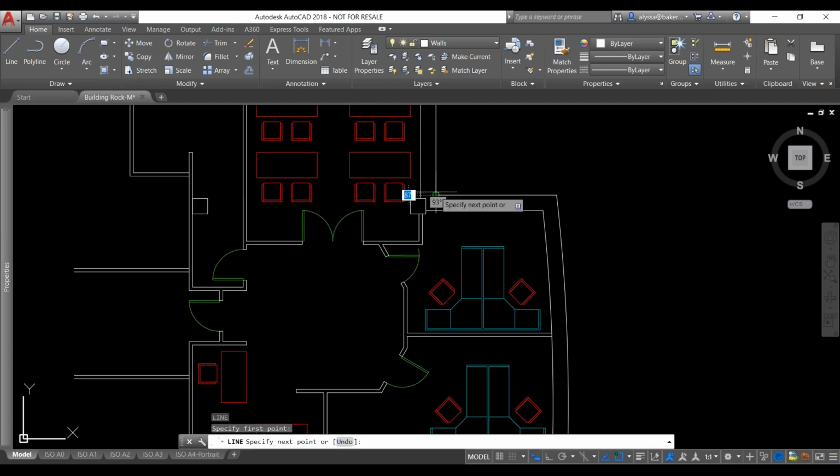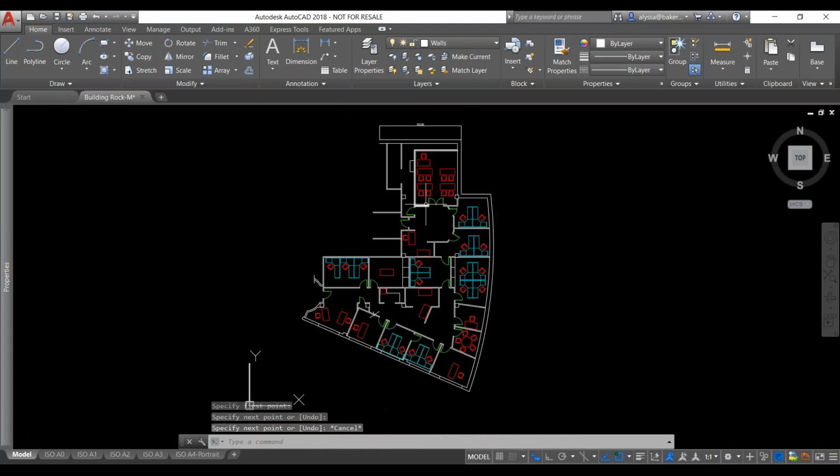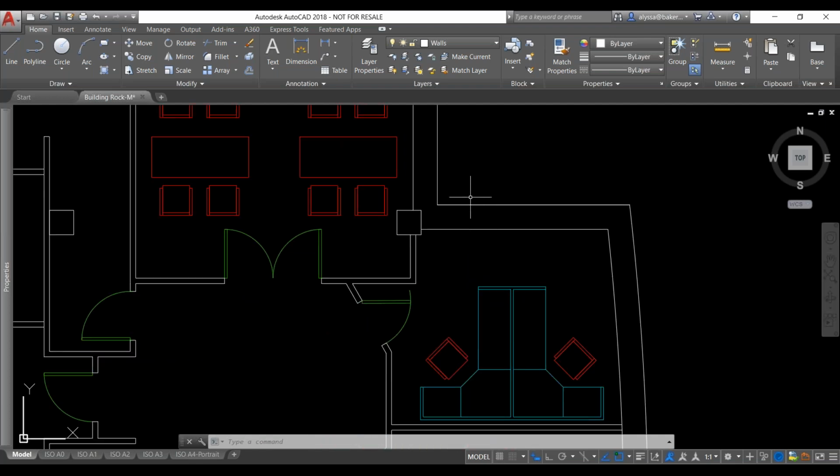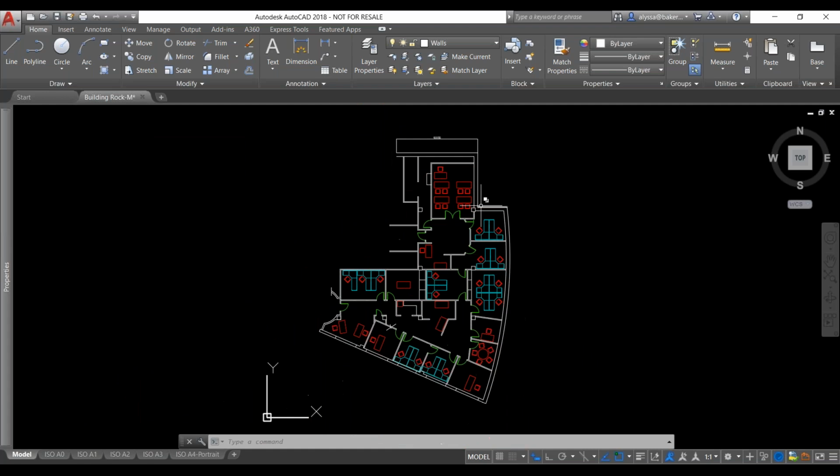So you might have lines on top of lines like that. You know, sometimes I know people, AutoCAD users especially, complain about the exported DWGs that come from Revit, that lines are on top of lines in this instance like that, and that's only because we're converting a 3D model into kind of a 2D space or 2D view. So lines on top of lines is a very common thing. So maybe something that you could use is overkill.